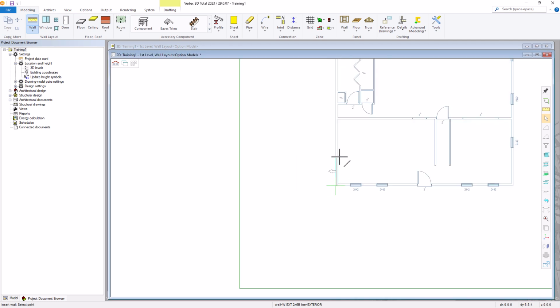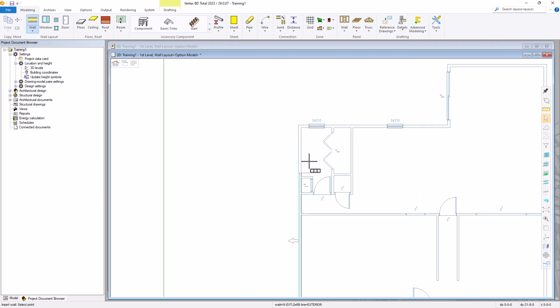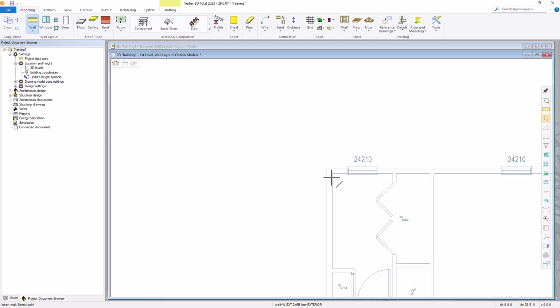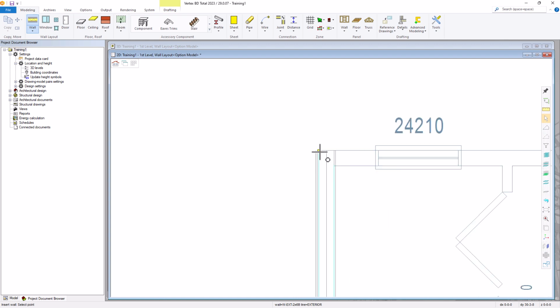Everything's correct. Now we'll go in and select the next corner. It's important when you're selecting corners, and in this case we have a very clean CAD drawing, very simple, not a lot of line work on the exterior wall, but in other CAD files you may see a lot of lines. So make sure you're zoomed in fairly tight so that you know you are selecting the correct corner and not selecting someplace out here, which would cause a skew in your line. You want to make sure you're truly locked in on what you want to select.